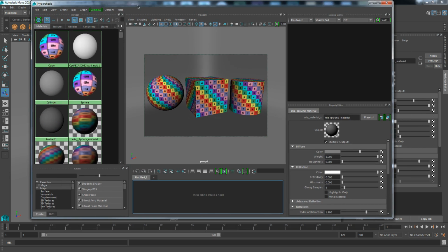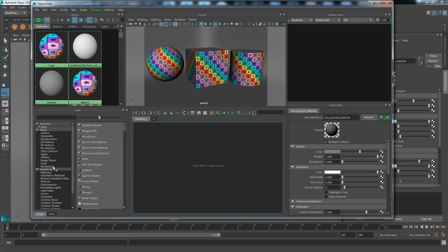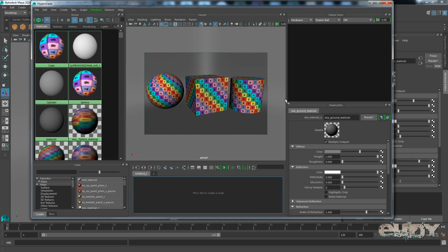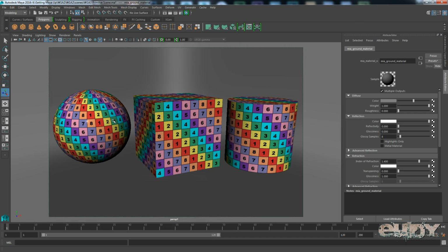And so when we're going into our overview of our shaders for Maya, we've got Mental Ray shaders down here that we can use, which the Mia material is the main one to use. And those are physically based shaders. They're just much more accurate, photographic looking. And then I showed you how to put your mapping coordinates on those, and then kick out our final render.